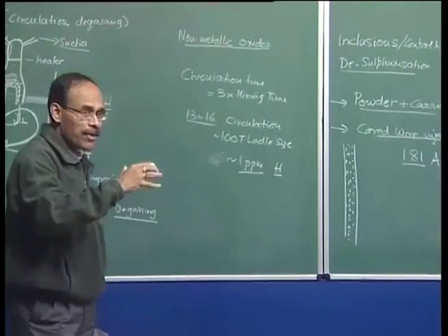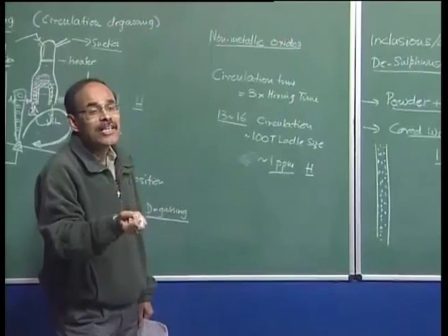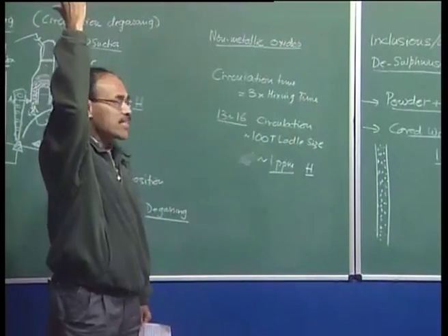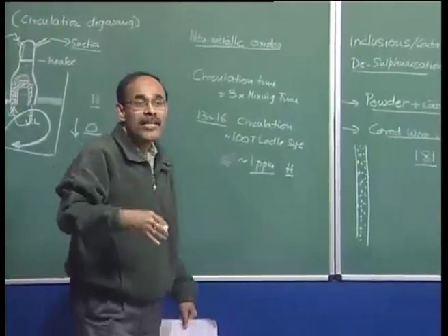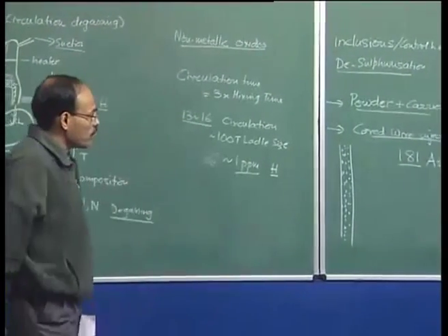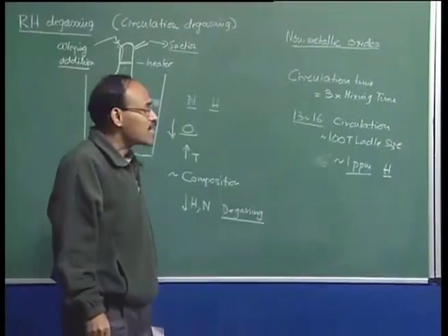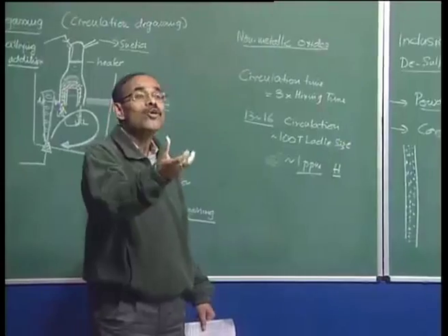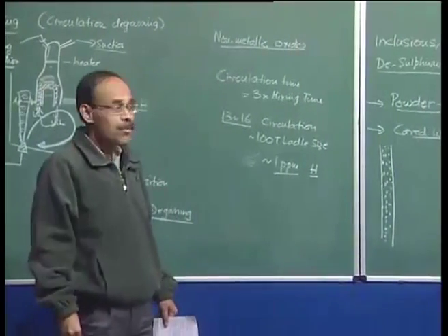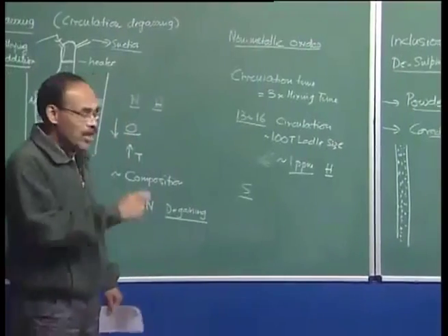The vapors being lighter, they will immediately try to come out of the melt itself, and if they do, the contact time between calcium and molten steel is going to be extremely small, and as a result you will not be able to dissolve a significant part of the calcium, because if sulfur is sitting in the melt in dissolved form, you want calcium to react with this sulfur.